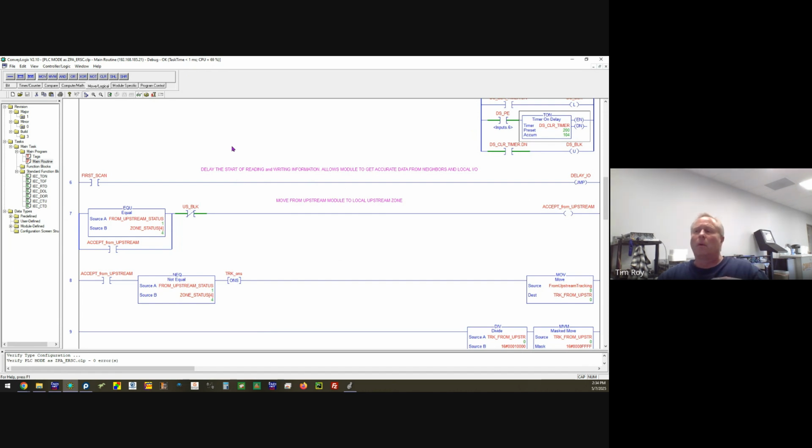And what we worry about on the CPU usage is when you get too high, the processor is running this ConveyLogix program instead of also being concerned about communications to other cards or properly running motors. It interferes with other tasks of the processor. So that's why we want to make sure the CPU usage doesn't get extremely high.